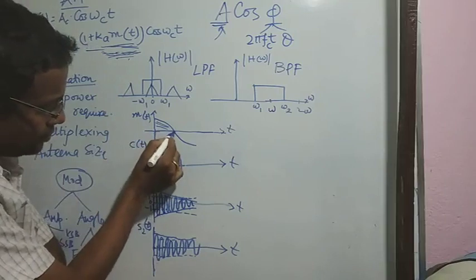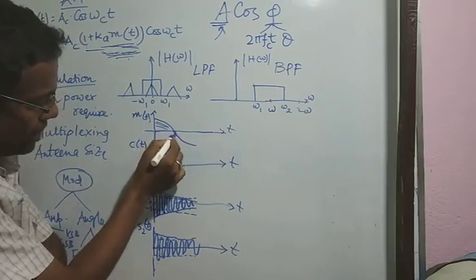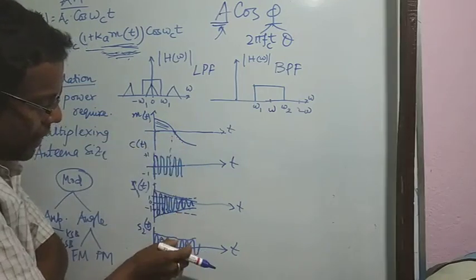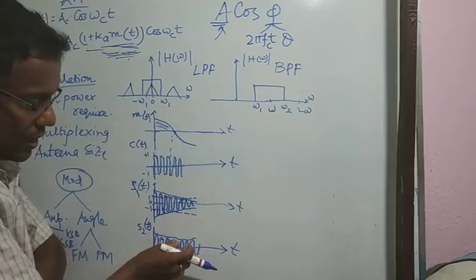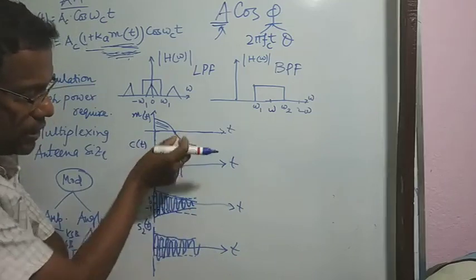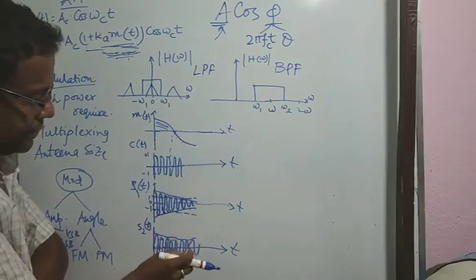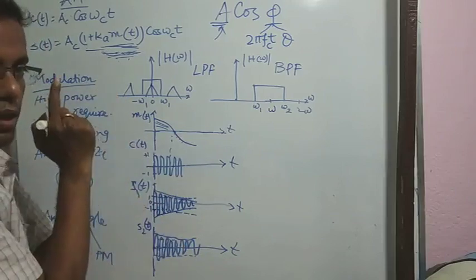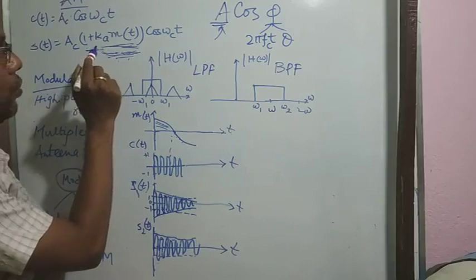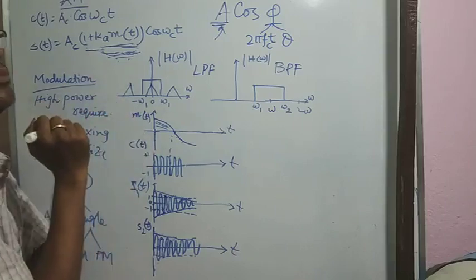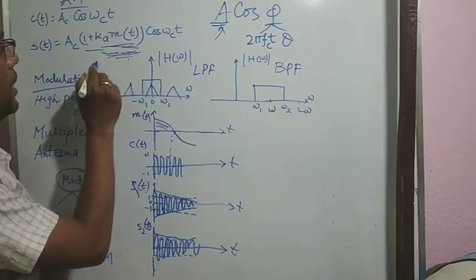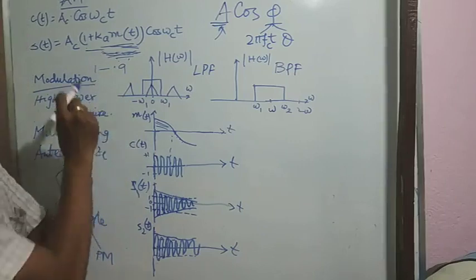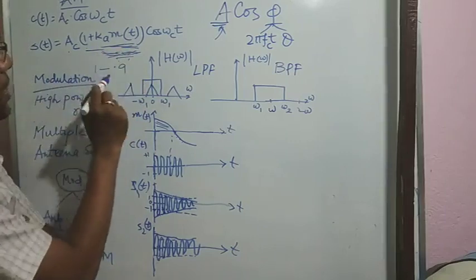You see, from here, in this part, the amplitude of the carrier signal starts reducing due to the negative part, and when this Ka m(t) will be, say, minus 1.2. Initially it was, say, 0.9, 1 minus 0.9 at any instant. So it is 0.1 Ac cos omega_c t.